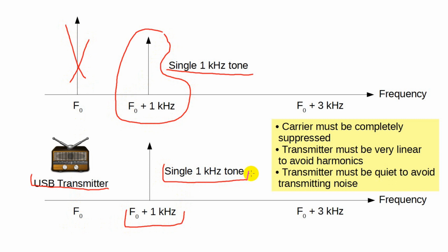Yes, it is. But I point out that for this to work, that is, generating a single transmitted tone using an audio input, the carrier must be suppressed as much as possible, as is normal SSB practice. The transmitter's audio and signal circuits must be as linear as possible, otherwise harmonics will show up, and the transmitter can't add broadband audio noise. It has to be quiet.